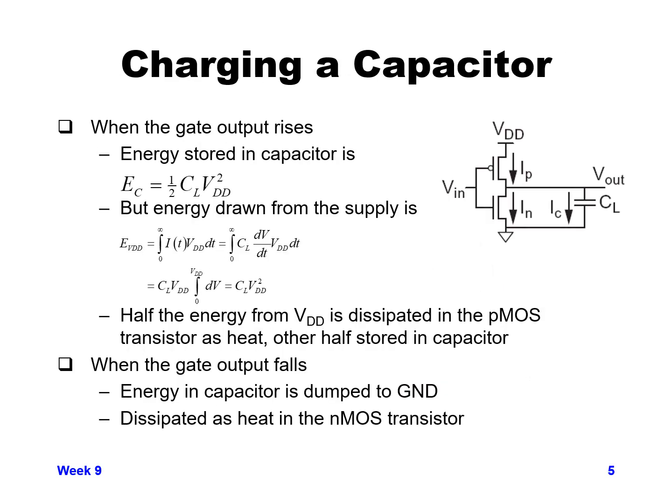In the previous slide, I said I was talking about power, but when I got to the capacitor, I only covered the energy stored in a capacitor. And you might ask, why didn't you talk about the capacitor consuming power? The reason is an ideal capacitor does not actually consume power. A capacitor only stores energy.